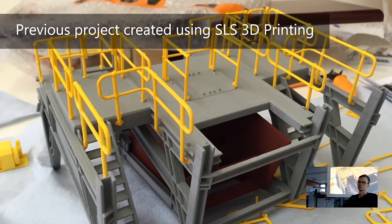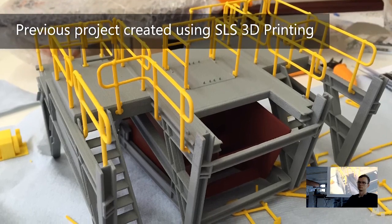So, as someone who's worked on SLS builds before, shrinkage is a major issue with even the most expensive SLS systems. And that's because the nylon powder, after the build is complete, shrinks on itself. And you think, okay, I'm used to shrinkage with ABS printing, fine, I understand. It's not that simple. Shrinkage on SLS systems is non-uniform. You have X and Y shrinkage, and then you have Z shrinkage, and it's a different percentage. So hopefully, depending on the software that is brought out with the Sintering and Fuse 1, it compensates for that, but there'd definitely be a bit of dialing in for that shrinkage.